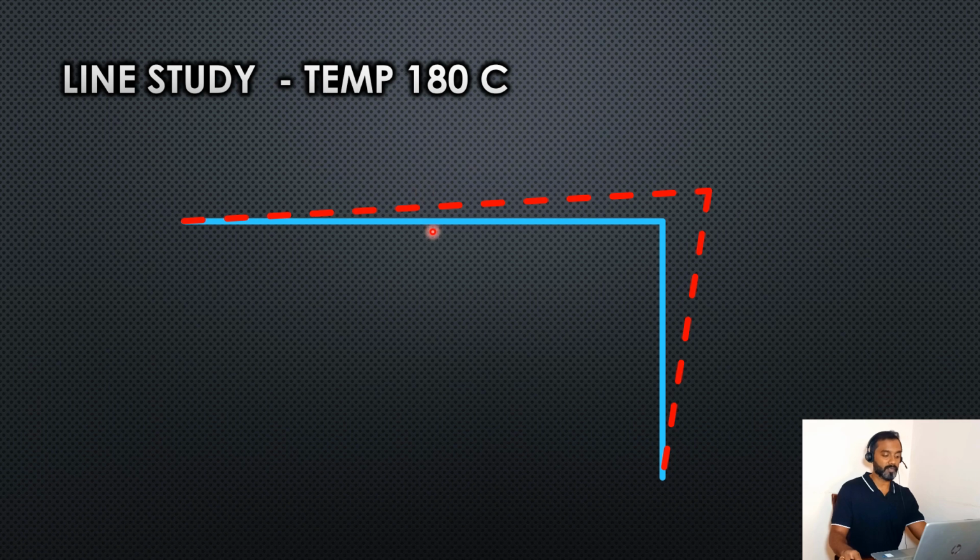So this is why you have to understand the stress analysis. In stress analysis, people put multiple rests and guides in order to limit it actually, because if the expansion is more, it will hit the nearby line, correct? So you have to limit the expansion. At the same time, you cannot prevent the expansion. See, expansion naturally has to happen. If you stop this expansion, the line will get compressed within and it will get damaged actually. So you have to allow the expansion, but make sure it will not hit the nearby line. So accordingly, you have to provide the support actually.